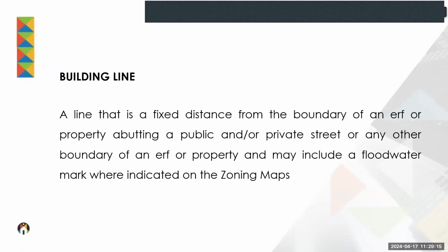And again here, don't just assume that if the town planning scheme says that the building line is X meters, that it will indeed be only that. There might be a restrictive condition in the title deed that might require a much bigger distance, and that means that that must first be resolved.